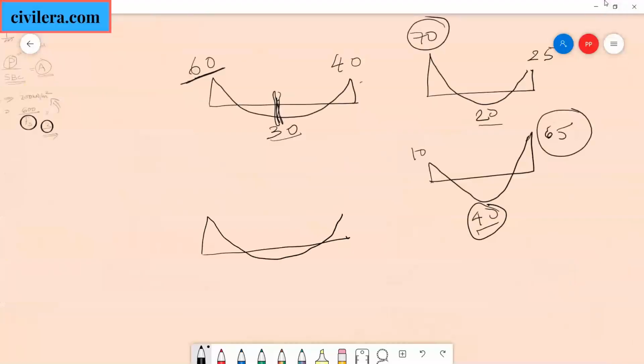First, draw the first load combination bending moment diagram. Over that you superimpose the second load combination bending moment diagram. Over that you superimpose the third. Once you superimpose all 26, you get one bending moment diagram superimposed with all 26 load combinations. That we call the factored or unfactored, whatever you choose, envelope of the bending moment. You can call it an envelope of any force. It can be an envelope for shear force, or any force for that matter. Here it is an envelope of the bending moment diagram.